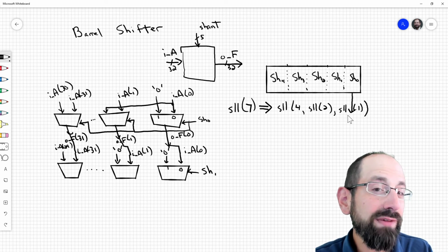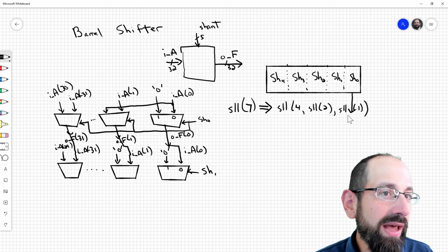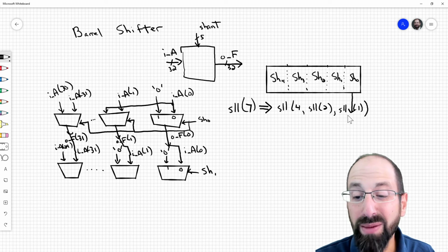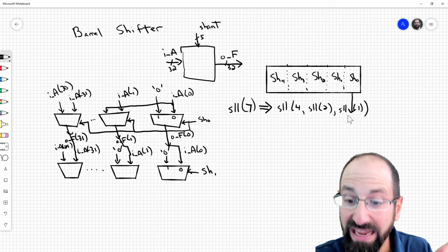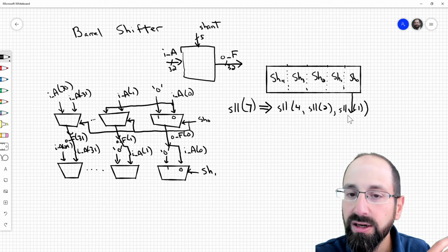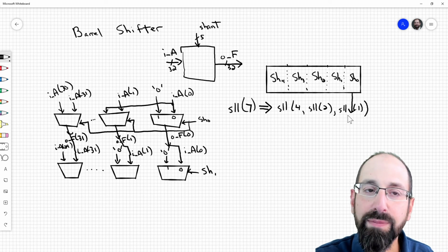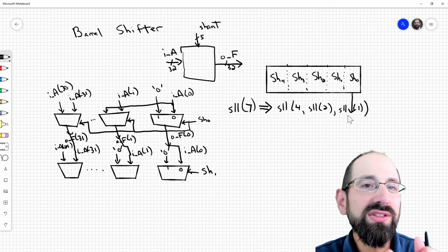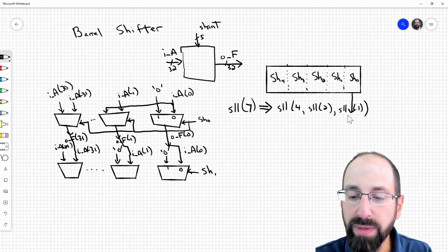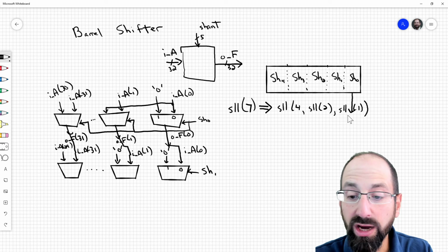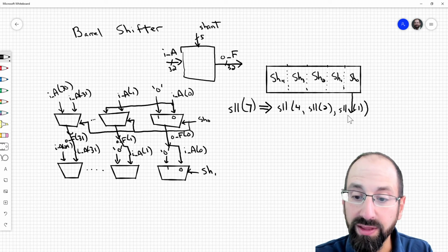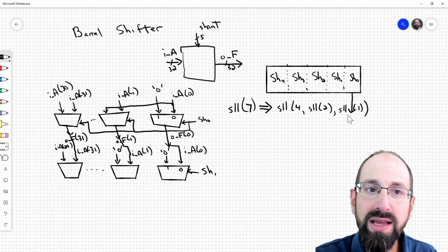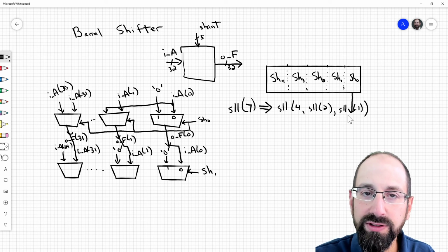Likewise, arithmetic shifts versus logical shifts aren't so bad either. We just have to be careful. Instead of always knowing that we're shifting in a constant, maybe it's the sign bit that we're shifting in. But it's the same concept of this barrel shifter, of these 5 stages of shifts happening. I think if you start with this diagram, and label your signals carefully, this isn't going to be too bad. We have to be careful. We can call the ports on our mux something, but the internal signals have to have clear and unambiguous labels to them so we don't inadvertently have multiple drivers in our design.